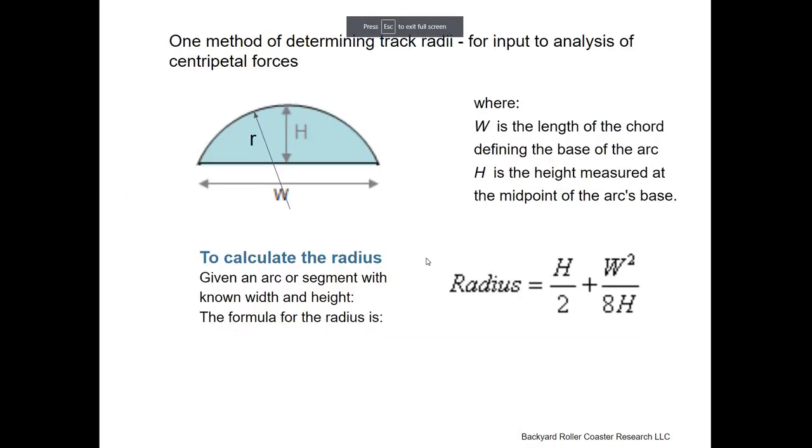So switching subjects here again. You want to find out what the radius is, and in other videos I show how to hot form the PVC 1.5 inch pipe with hot sand. You can also do it in the sun if you're not trying to get too big or too small of a radius. And one method to do that is to just put a straight, like a 4-foot level across the curve, and by this equation you can find out what the radius is.